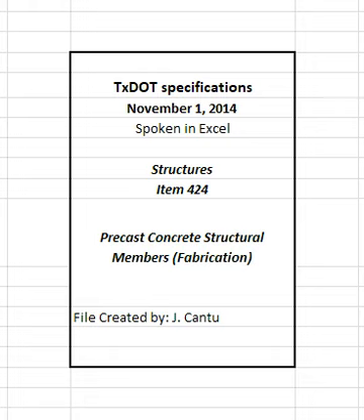Pressure gauges or electronic pressure indicators must indicate the load directly to 1% of the maximum gauge or sensor/indicator capacity or 2% of the maximum load applied, whichever is smaller. Calibrate each jack and its gauge with the cylinder extension in the approximate position at final jacking force. Jacks and gauges for post-tensioning and single-strand pre-tensioning must be calibrated as a unit. Have certified calibration charts furnished by an independent laboratory with each jack and gauge used on the project.